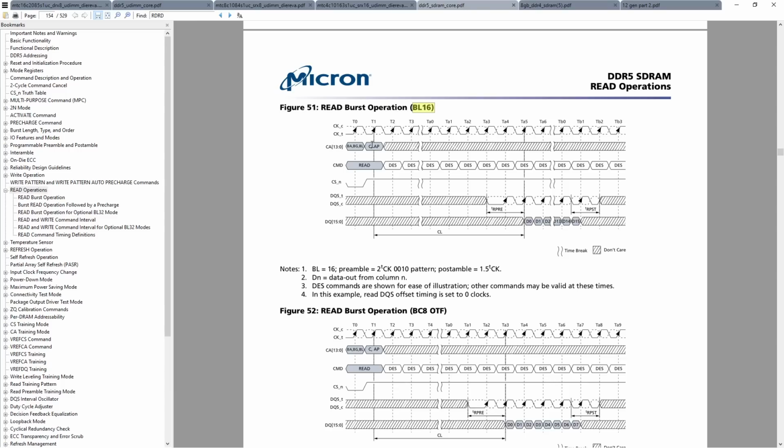There is a funny penalty to having a bunch of independent memory channels, and that is that your worst case scenario memory latency actually gets worse. Or more like your memory latency for single accesses gets worse, because the CPU has to go and find which memory channel your stuff is on.